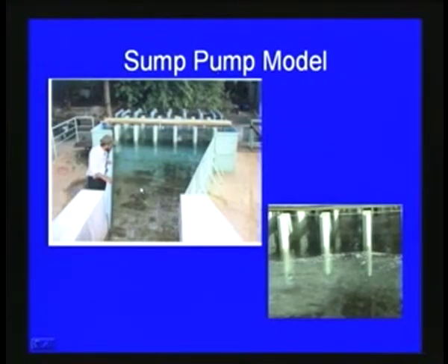Now, before closing this section, let us briefly discuss some of the models. The first one, as I mentioned earlier, is the sump pump model. Modeling has been done in our hydraulics laboratory. This model has been built to a certain scale. Here you can see the pumps are located here, and a channel to simulate the forebay conditions. This is the flow coming, and our aim here is to see whether the forebay given is okay, what turbulence is generated, or what happens in this sump where the pumps are taking water.